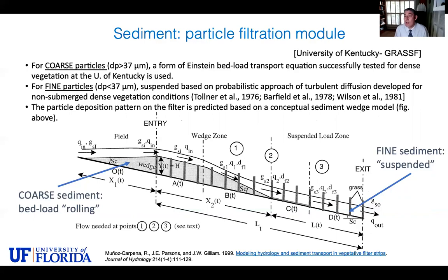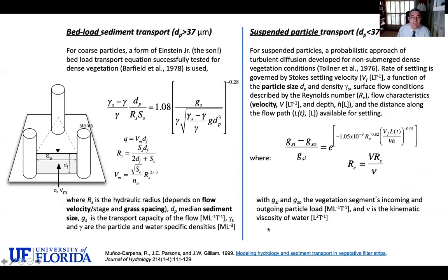Stokes law that we call, okay, and ultimately the turbulence of the flow, which could keep them afloat, because the turbulence could be pushing them up at some point. So the turbulence of the flow, the sedimentation characteristics of the particle, and the velocity of flow will determine the settling of these fine particles. All right, so those 2 classes are modeled independently.